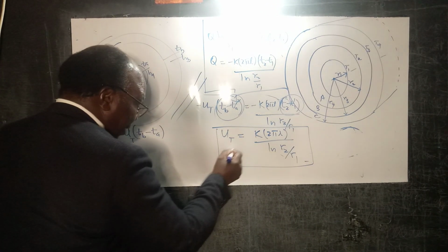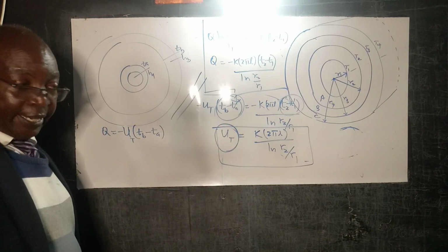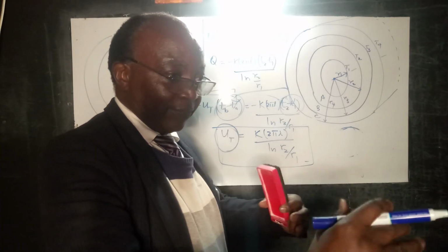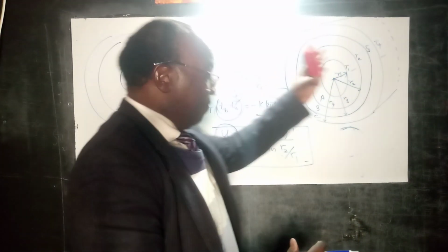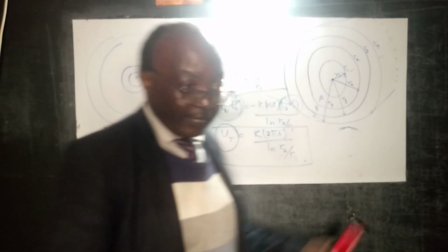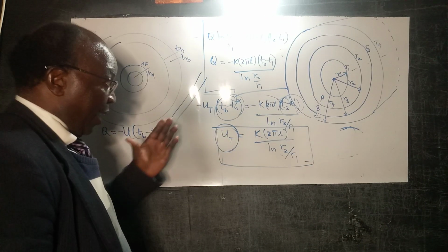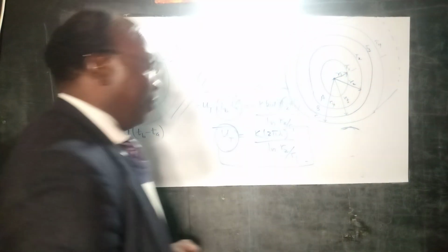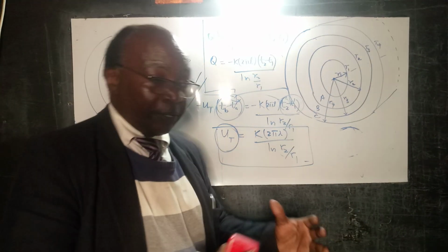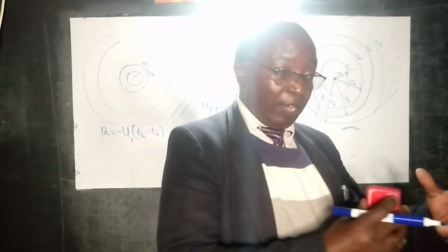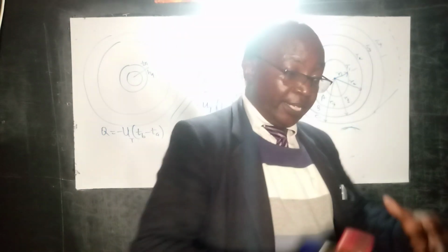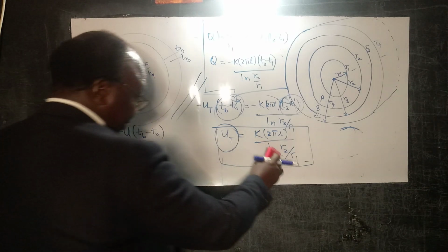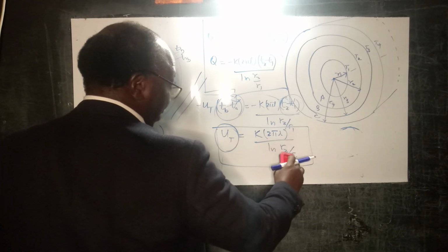But remember, in the overall heat transfer coefficient, we have the individual heat transfer coefficients corresponding to the various surfaces in that particular system. One from R1 to R2, R2 to R3, R3 to R4. We saw that in the composite transfer of heat in a system consisting of several walls. This has just confined itself to transfer from R1 to R2.